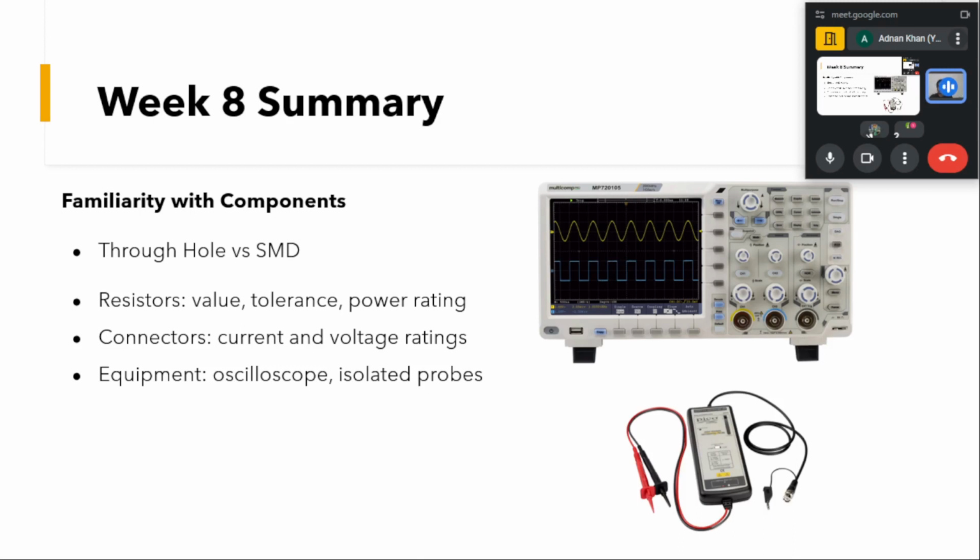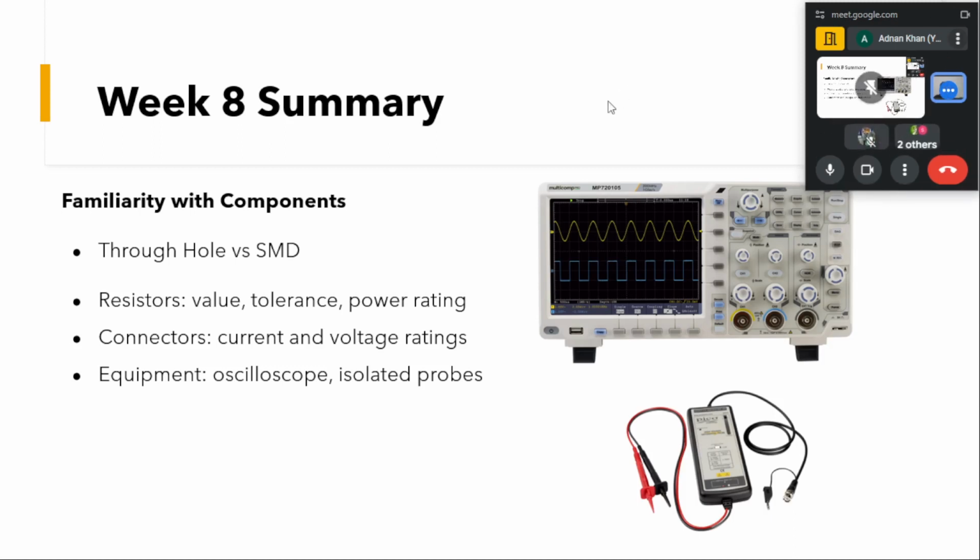If we want to probe different voltages or currents which have different grounds, we should not do that using single-ended probes, because the two grounds may get shorted, and it may damage the oscilloscope. If there is a fault on this, it may get propagated to other parts, or damage this. For that, we usually use isolated probes.